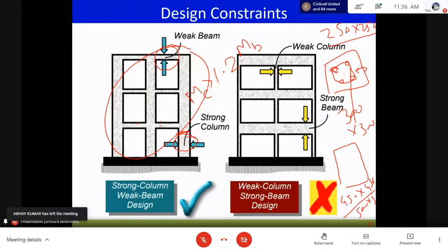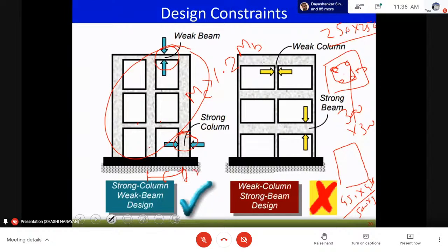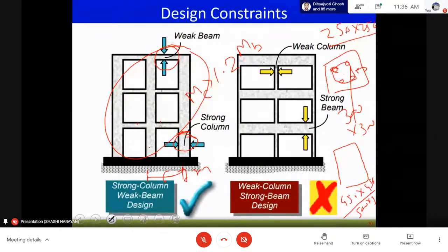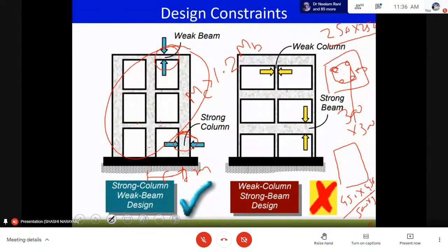So generally we want at least 6 to 7 meters distance between these two. That is, the span of the beam is approximately 6 to 7 meters. If we do not have this span, then we are having a large amount of concreting to resist a small amount of forces. So for an economical design, we want beam spans of 6 to 7 or 10 meters nearly. In that case, we'll have a good percentage of the material being used to resist our forces.